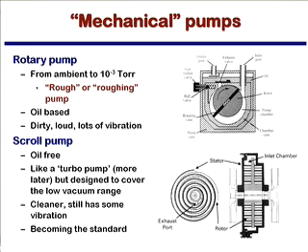The idea with these is that you are basically taking an air inlet. You have a rotor that goes around, and it just kind of squeezes the air out the other side, okay? So it's off symmetry in its rotation, and as it rotates clockwise here, it basically traps the air here and then pushes it out the other side, okay? Very simple mechanism and the like. They work very well for ambient to 10 to the minus 3 torr. These things are called roughing pumps or rough pumps because they're just getting rid of most of the gas when initiating the vacuum sequence. Now, some disadvantages to some of the rotary pumps is that they are oil-based and they can be dirty and loud as a result.